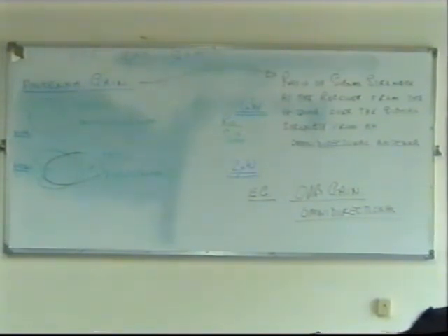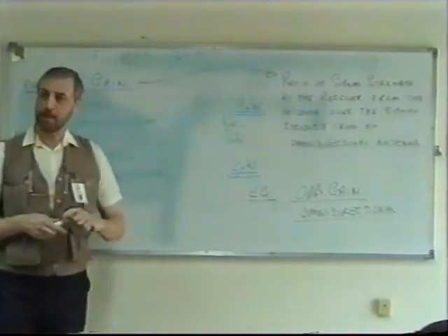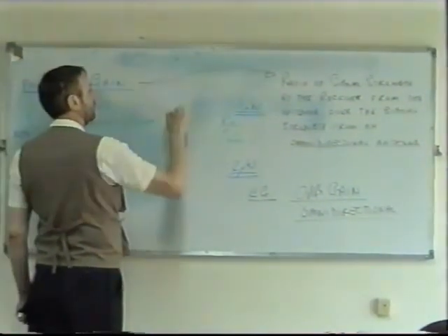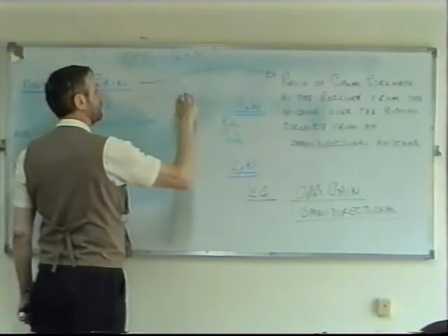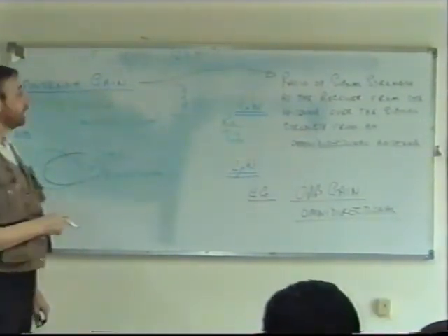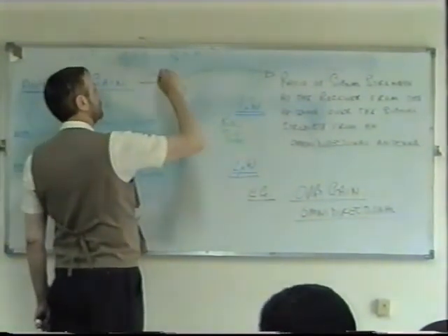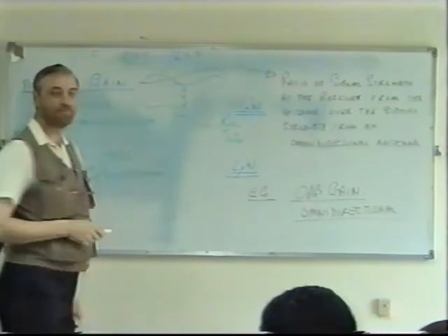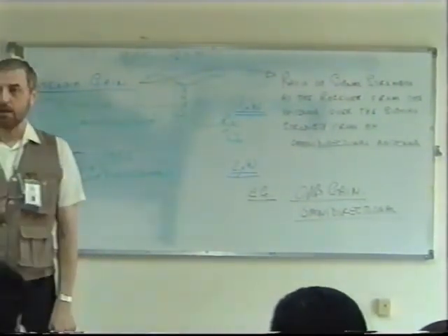It's useless. What about 6 dB? Well, you can get 6 dB gain on a stacked array. And remember what you said on Wednesday about stacked arrays. This is where we have a number of antennas under one another, and that does have a gain greater than 0. But the reason for that is because it cuts out the radiation from above and below, but it's all the way round. I'm not quite sure of the figure; 3 dB would be more like the mark.